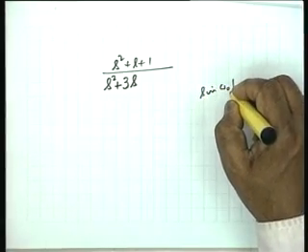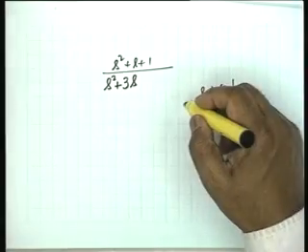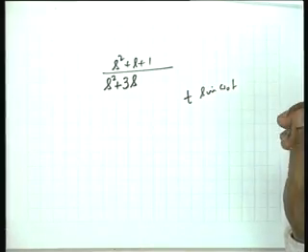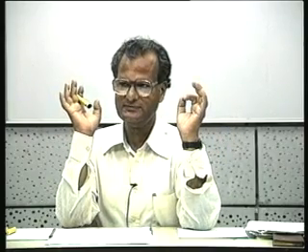Sir, why should poles on the j omega axis be simple? Well, that we have already elaborated. What does a pole on the j omega axis cause in the time domain? In the time domain, it is either a sine function or a cosine function. If there are multiple poles, for example a pole of double order, then this is multiplied by t. So from the definition of PRF, well, instability means that the real part condition shall be violated. Instability means that the real part, that is the power, can be negative.